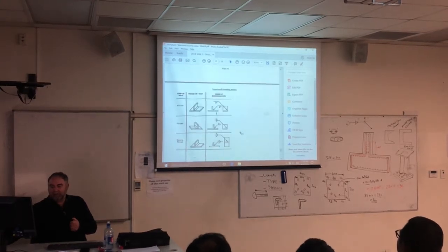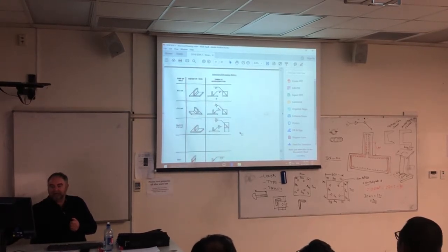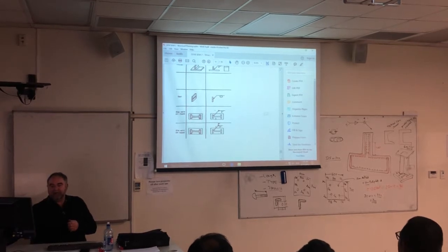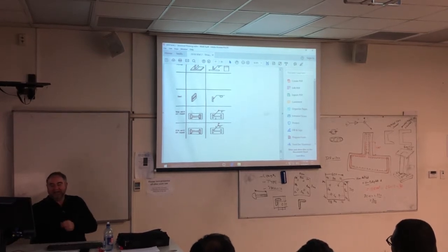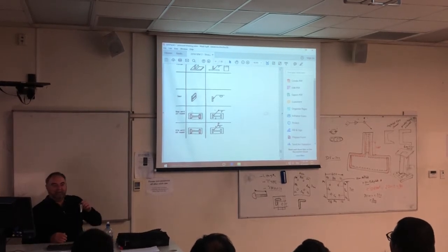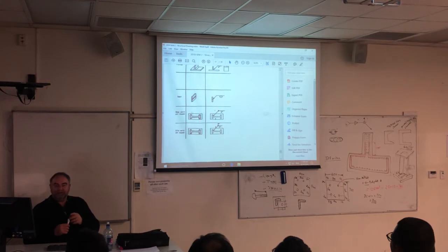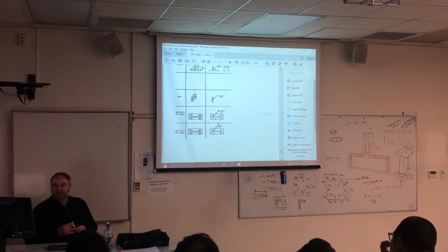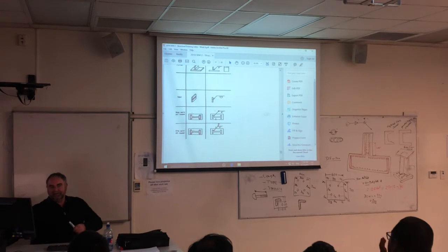Okay. There's a whole extra chart here of different types of welds, your fillet welds, your double welds, your seal welds. And here's my friend at the back there with the beard that was getting all upset about it. Yeah, so here's how we represent the plan view of a weld. Not the sideways view. The sideways view we use the symbol. The plan view we use the schoolboy's beard.